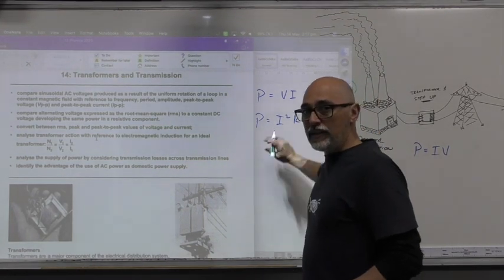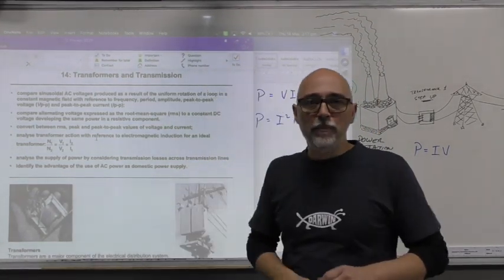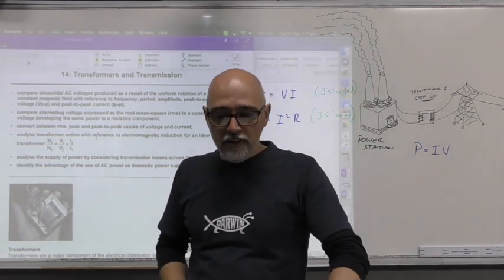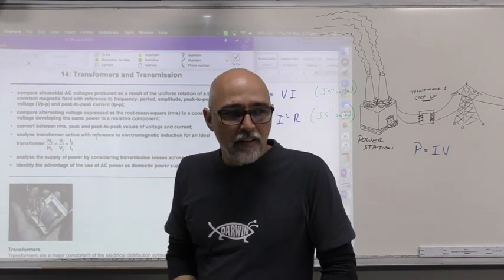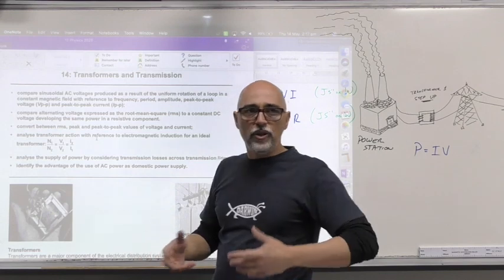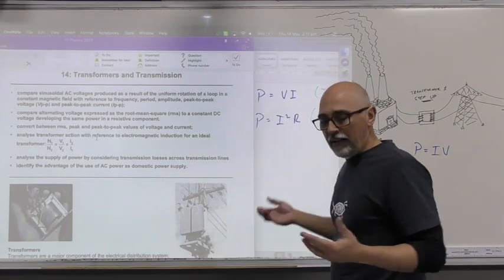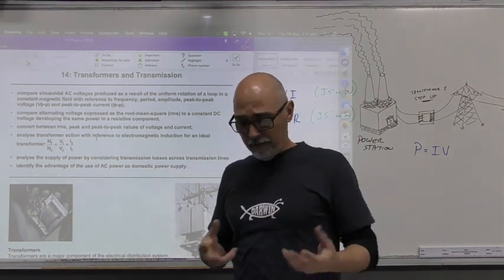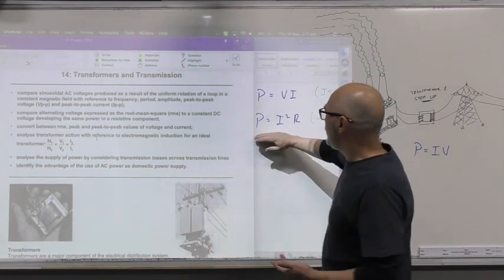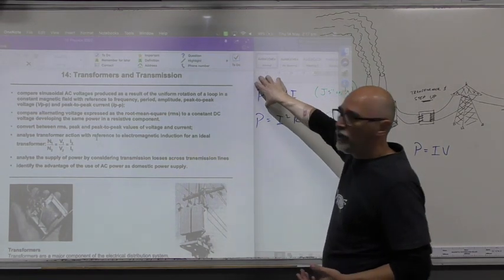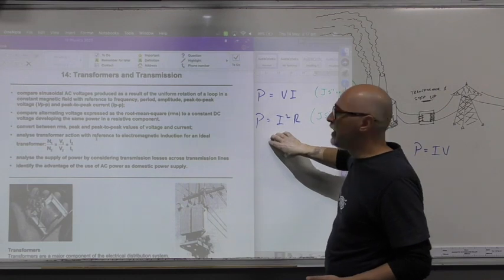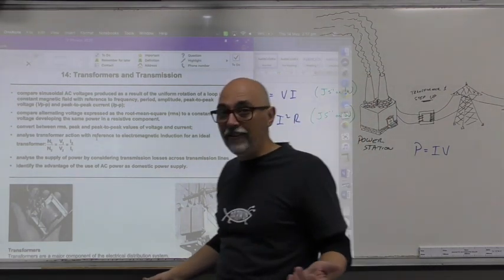This is often used to calculate how much power is lost in the lines, because usually in a question you'll be given what the resistance in the lines is, okay? You won't know the voltage or you won't know something else, but the values of the current and the resistance are often given to you there, or you find them quite easily, and that tells you, well, if I produce 1,000 watts here and I lose 100 watts in transmission, then I know up at the other end there's only 900 watts left.